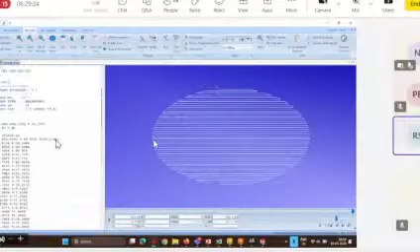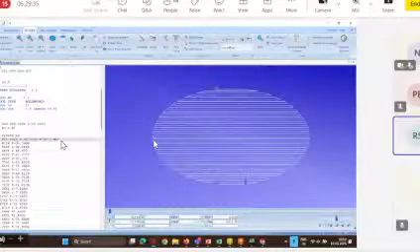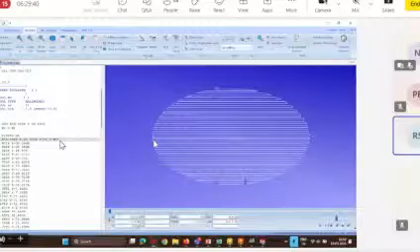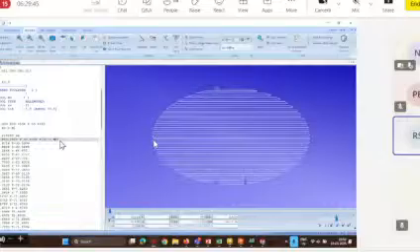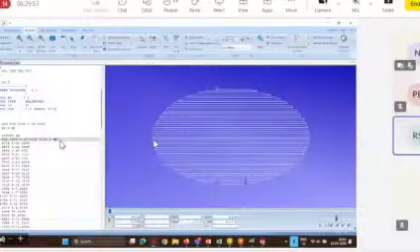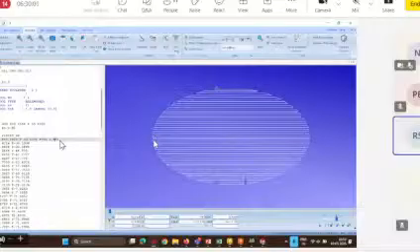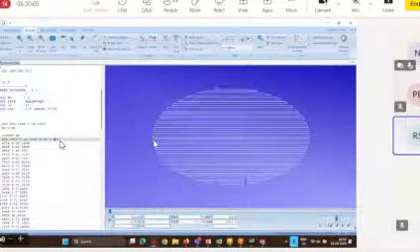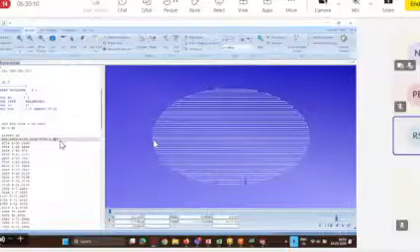I just like to highlight once again this M51 and M52 are nothing but the welding start and welding stop commands. So basically we are controlling the deposition process with the help of the NC file, M code basically. And to do so, we need to take out the two terminals from the welding power source, trigger source basically. Then we need to connect it to some solenoid which is connected to the PLC of the CNC machine. So whenever we give some M code defined by the logic ladder diagram, then it will automatically work.